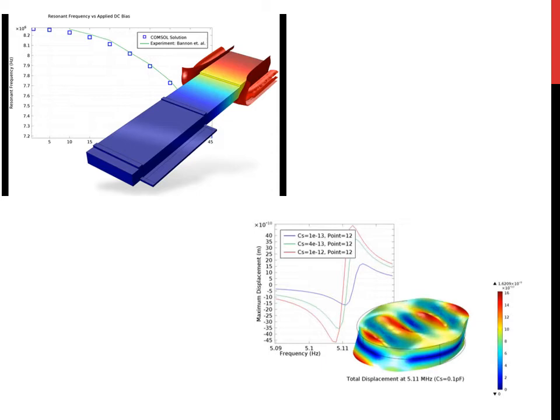And the second one is a piezoelectric bulk acoustic wave device using quartz materials. So from here we can predict the displacement at resonance frequency, and the simulation can also calculate in the frequency domain, where we can sweep the frequency of the device to predict the mechanical displacement.